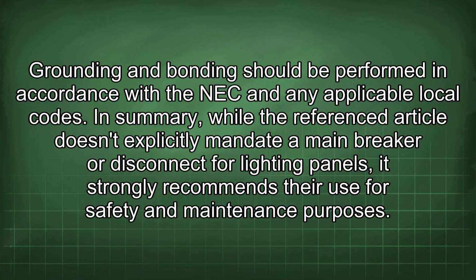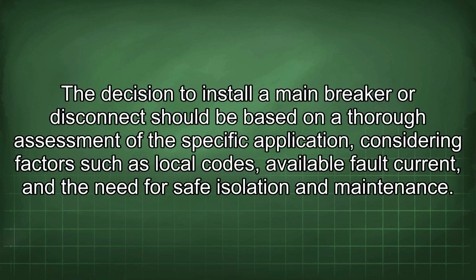In summary, while the referenced article doesn't explicitly mandate a main breaker or disconnect for lighting panels, it strongly recommends their use for safety and maintenance purposes. The decision to install a main breaker or disconnect should be based on a thorough assessment of the specific application, considering factors such as local codes, available fault current, and the need for safe isolation and maintenance.